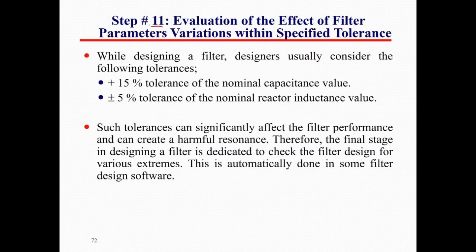Step number 11, evaluation of the effect of filter parameter variation with unspecified tolerance. While designing a filter, the designer should usually consider the following tolerances: plus 15% tolerance of the nominal capacitance value, minus or plus 5% tolerance of the nominal reactor inductance. Such tolerance can significantly affect the filter performance and can create a harmful resonance. Therefore, the final stage in designing a filter is dedicated to checking the filter design for various extremes. This is automatically done in some filter design software.